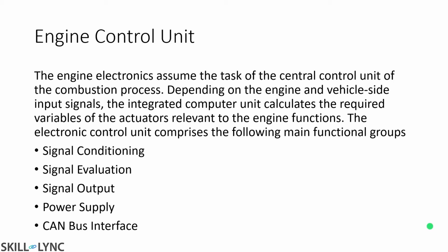The ECU is just going to take the output of the sensor, read what the sensor is trying to tell it, and then based on this output, make sure that the actuator knows what to do. This is what I've been saying from the very first lecture itself. I mentioned that the control system comprises sensors, actuators and software. The software is going to be the ECU in this case, and the ECU is going to be told what to do in which condition. It's going to be given a few conditions and told that if this is the case, do this.